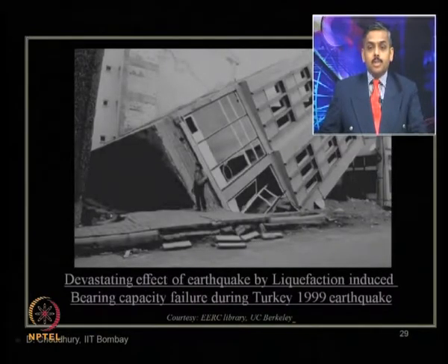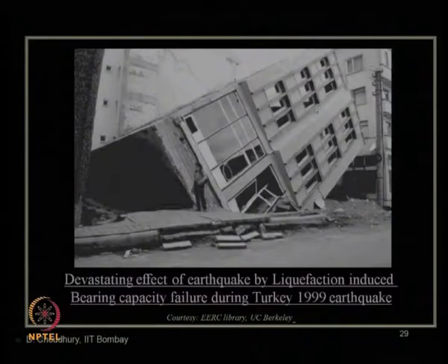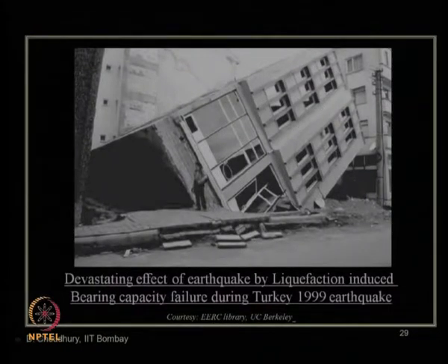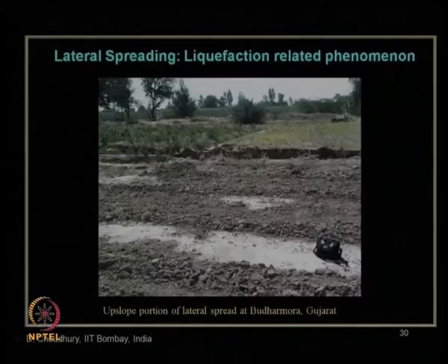This is another picture which shows the devastating effect of earthquake by the liquefaction induced bearing capacity failure during the Turkey 1999 earthquake. Here also one can notice there is not much damage on the superstructure, but the problem was with the soil liquefaction. That is the reason why geotechnical earthquake engineering needs to be studied properly to understand this problem and to make liquefaction resistant or earthquake resistant construction of foundations, taking care of the local soil conditions.